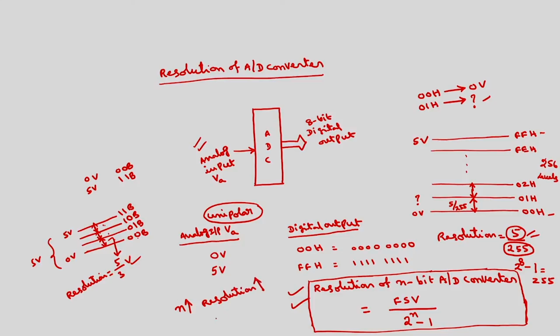But at the same time, the complexity also will increase. So because of this, there will be some compromise between the complexity and accuracy. Resolution decides the accuracy. Depends upon the applications. The applications where accuracy is more important, we will go for more bits of A to D converters, like in case of biomedical applications, MRI, if I want to convert the MRI information into digital.